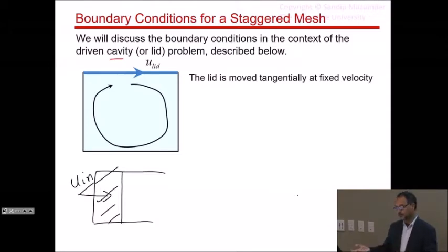Now, none of this you'll be doing in your homework, but I'm mentioning all this because you may encounter such situations for your research or some code that you're developing. Okay, so do not classify inlet and wall moving normal to the fluid as the same. They will not act the same way.